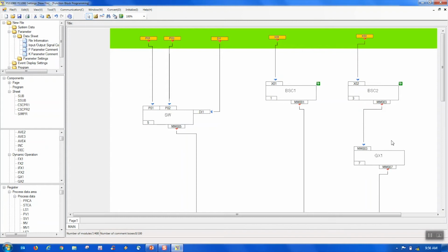So what we want to do is change the execution order. Since this block is directly before the g of x block, we need to make them sequential. So let's make this one 3, which it already is. Change this one to 4. If you go up to the icons here, you can hover and it'll tell you what the icons are, but we're looking for the change execution order.